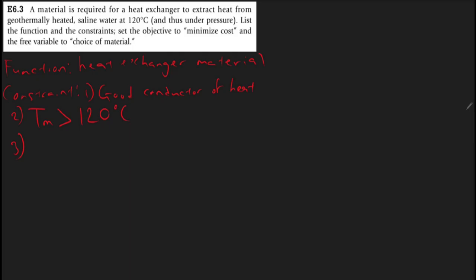For number three, what else do we need? You know that the material is dipped into salt water. So corrosion resistance. When you dip a material, salt water enhances corrosion. So it has to be corrosion resistant.